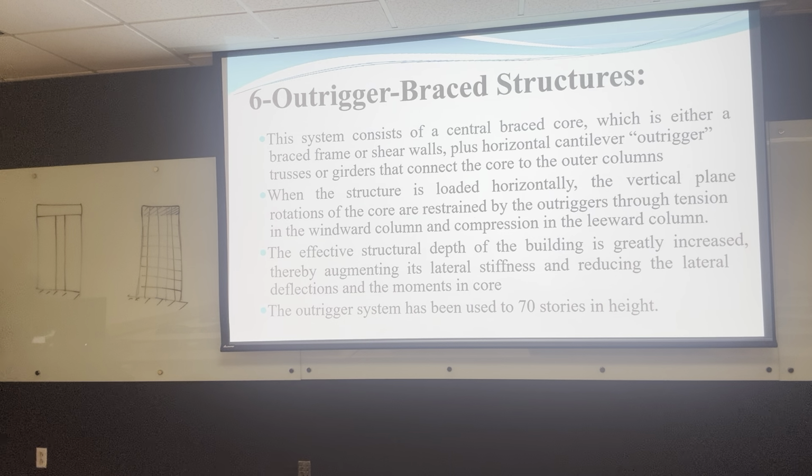So when this building gets hit with an earthquake, whatever this earthquake looks like, let's say this is the acceleration of the ground, there are base forces hitting the base to shake the building. So this building wants to turn that way. There's a bending moment, like all the masses want to be thrown that way. So there's a bending moment on this shear wall. If you look at the stresses of the shear wall, there's a lot of tension here, there's a lot of compression here, and this is the stress down there.